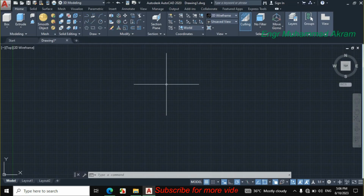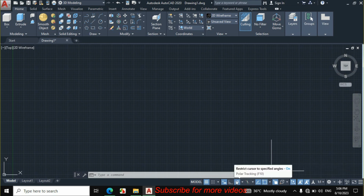But before starting 3D drawing, make sure that you turn on all these options. The first and important option is selection cycling. This option is very important while drawing a 3D object in AutoCAD, because sometimes we select a solid and sometimes we select a line. For example, if we draw a line on the solid surface, it is very difficult to select a line or a solid. From this option it is very easy to select a line or a solid. The other important options are dynamic UCS, dynamic input, polar tracking, and object snap. All these options are very important while drawing a 3D figure.